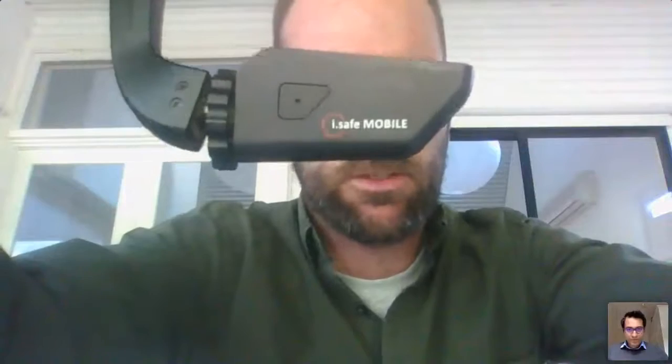Perfect, thanks. And there are more questions coming up. David has asked, what are the options if you only have 4G LTE in a hazardous area? So this company here, iSafe Mobile, provides an intrinsically safe 4G LTE, and otherwise there are phones and tablets that are able to be used as the hub to tether Wi-Fi.